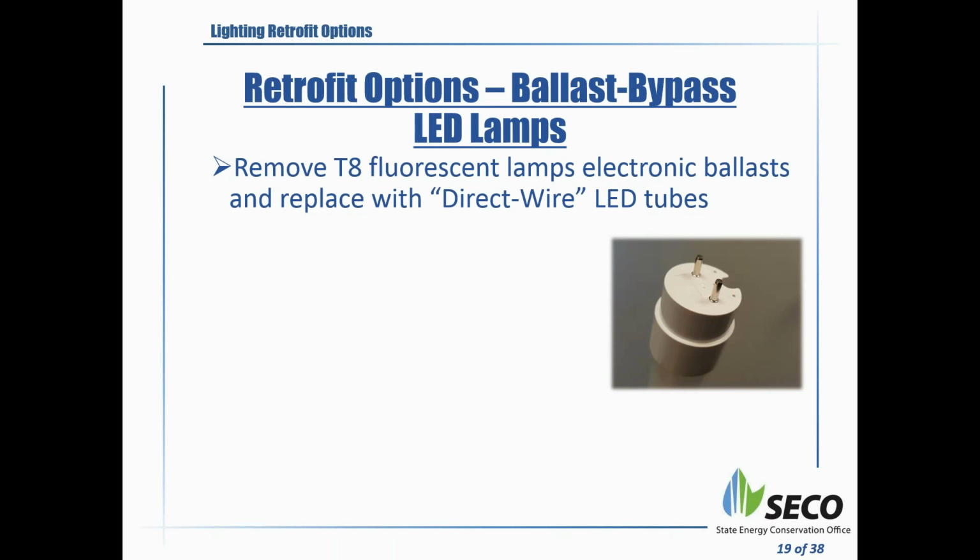Retrofit options: ballast bypass LED. So this is also LED. When you look at this lamp, you won't be able to tell the difference. It looks very similar to the regular LED tube lamp, or to the fluorescents, but they are direct wired. In other words, they have a built-in driver in there, so theoretically you don't need a ballast or an external driver to run these things.